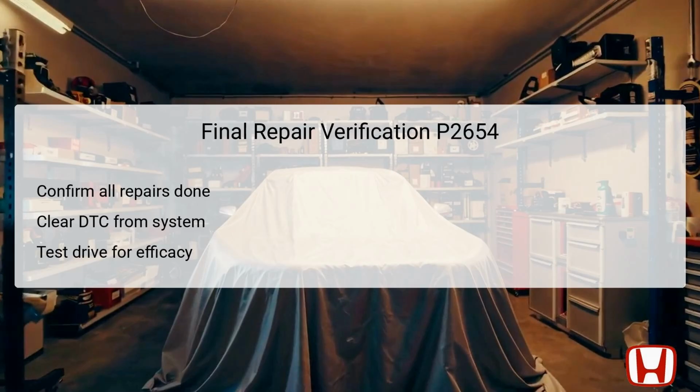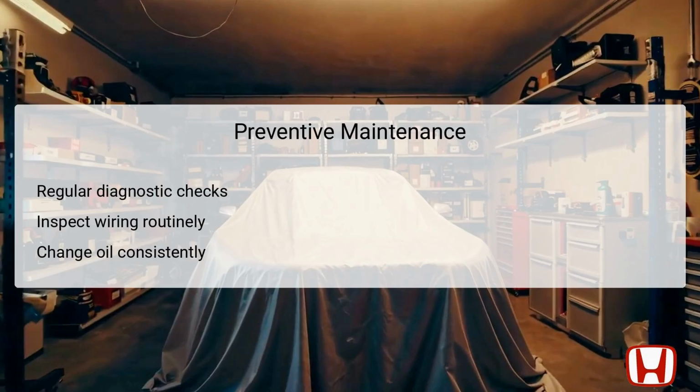Pay special attention to any unusual symptoms or warning lights during the drive. A successful resolution means that the engine is running smoothly and the VTEC system operates as expected without triggering DTC P2654 again.